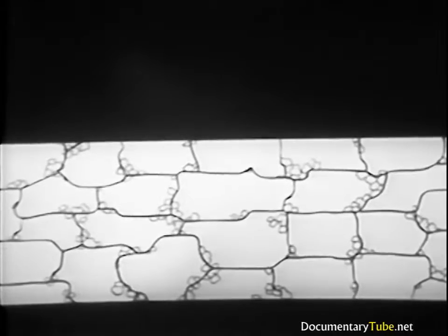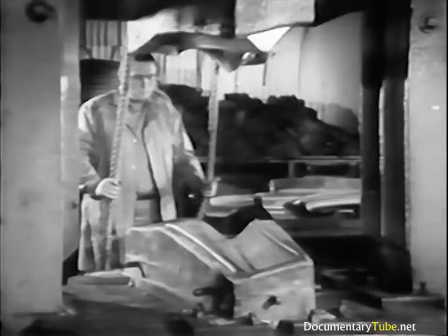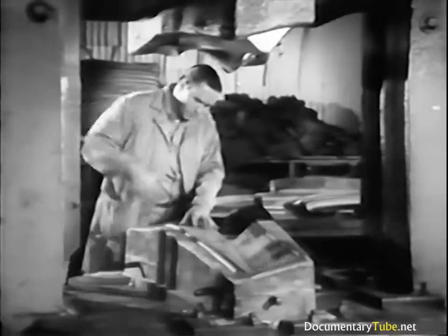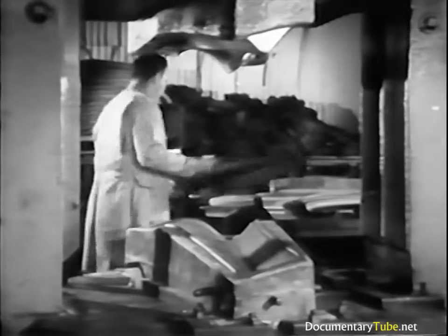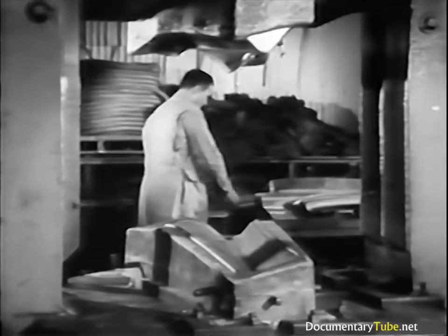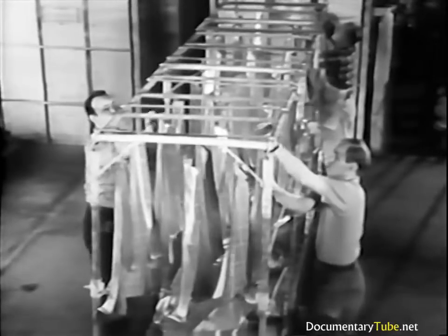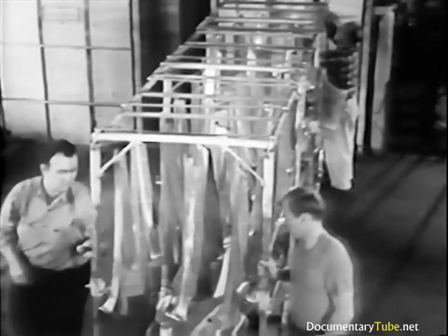But since the plastic deformation is generally more severe, fragmentation and crushing of the grains also occur. The fact that severe cold working results from such operations as drop hammering and deep drawing gives rise to the need for an annealing or softening process between blows or other forming operations in order to prevent rupture of the parts.